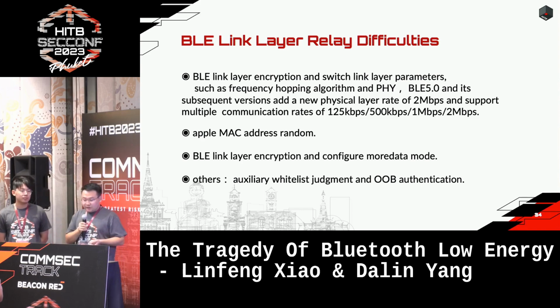The difficulties in the research process are as follows. First, data encryption at the link layer, and the configuration parameters at the link layer are changed in the interactive process. The most obvious difference is that the physical layer transfer rate parameter changes from 1 megabit per second to 2 megabits per second during data interaction.